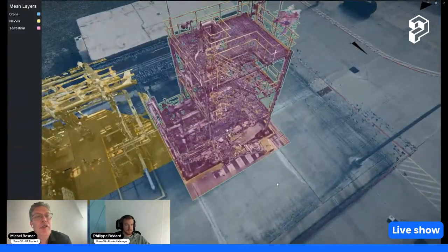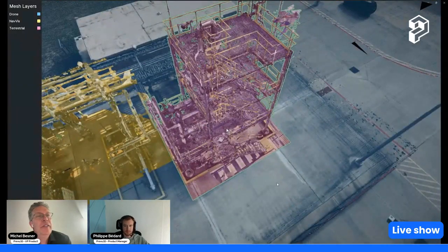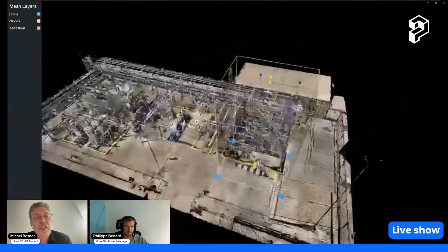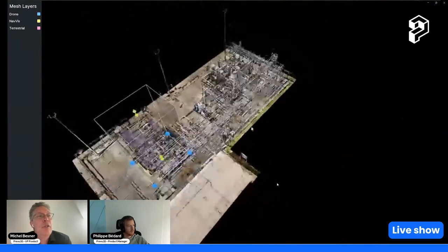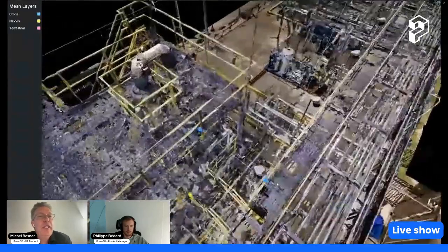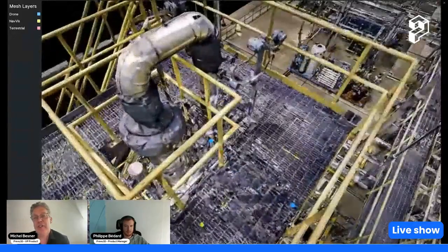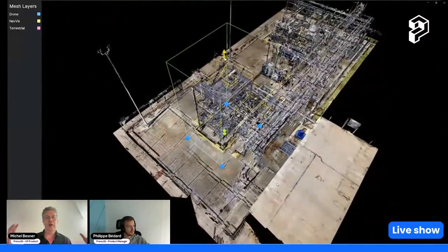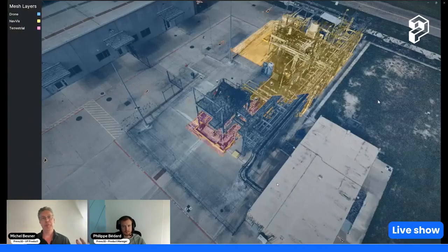Here you're seeing all the blue is basically drone data, the yellow is a Navis VLX, and what was in purple was actually a terrestrial scanner on the same space. And so we're creating this tool where you can actually create bounding areas and really construct a volumetric environment of a combination of multiple scans.